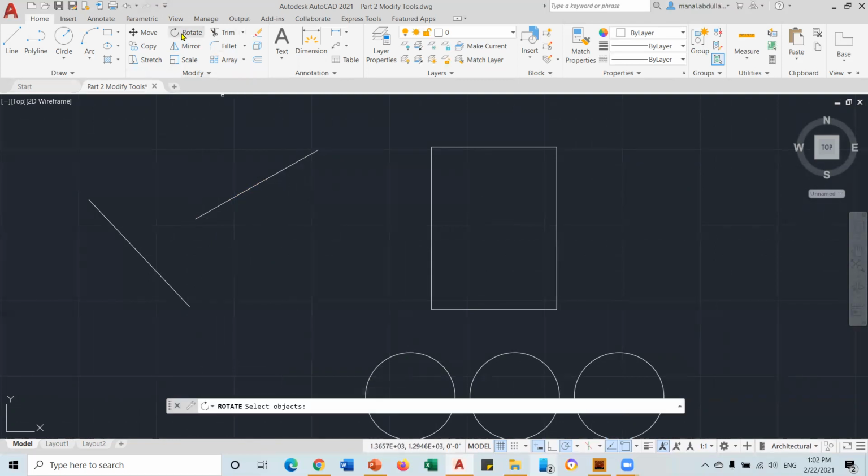If you rotate negative angles, let's see here. Let's do select object, enter, from this point. If I put minus, so let me put here minus 60. Okay, so negative 60, enter, so you go down.